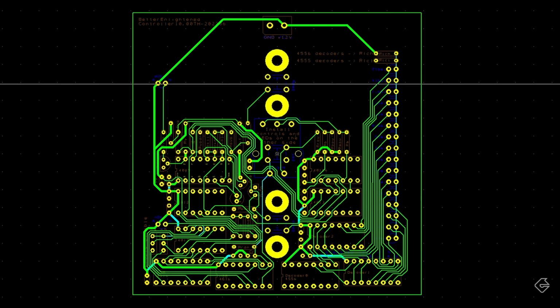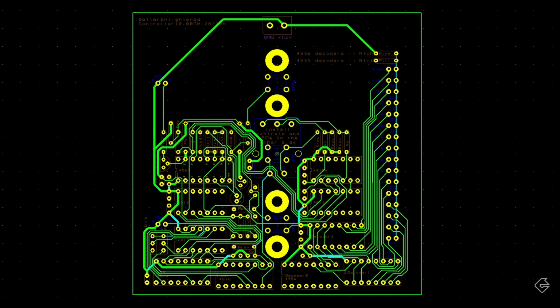The first thing we're going to do is remove the traces that we had put in previous episodes connecting all the ground pins. There, the traces are now gone, but if I highlight the net, all of the pads that belong to the ground net are still being highlighted, and we want to be able to connect all these. In this particular software, it's really easy. All we have to do is draw an outline of the shape, which is basically the boundary of our copper pour, and then we're going to pour the copper. So let's start with the shape.